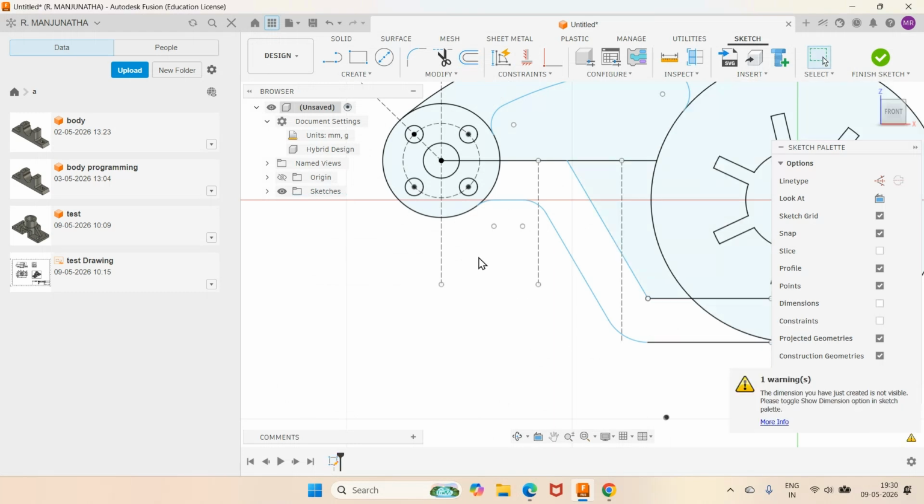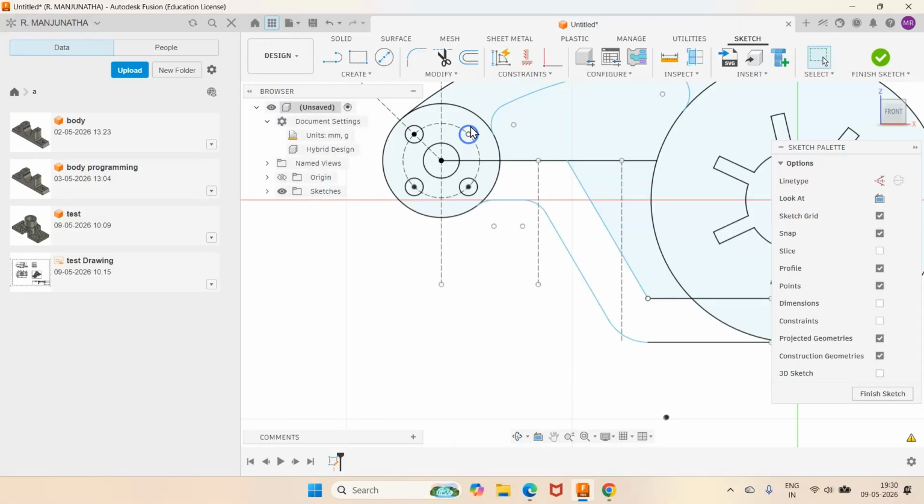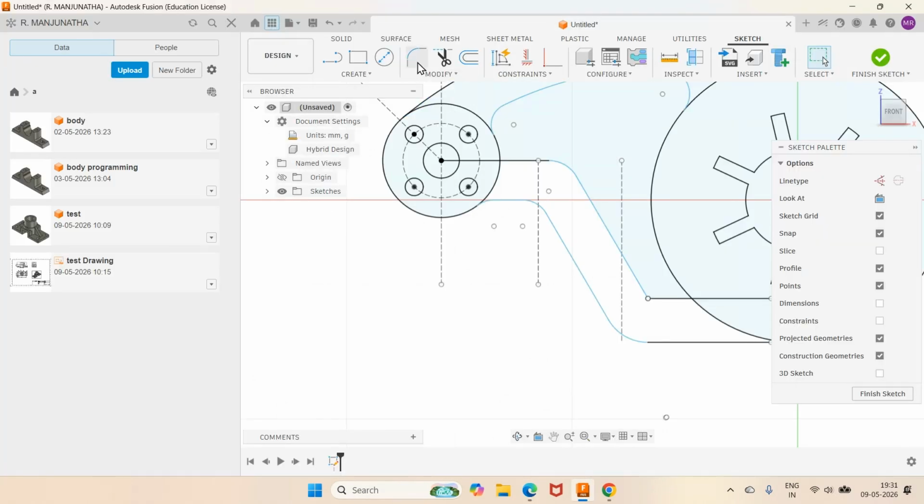Now, so one should do that. Now what I want is this radius to be 14. So I will go for fillet, take this line and this line, radius is 14. Yeah. Now we have this. Similarly on this side, radius is 8. Okay. Go to fillet between this line and this arc. Radius is 8. Okay. We have this.